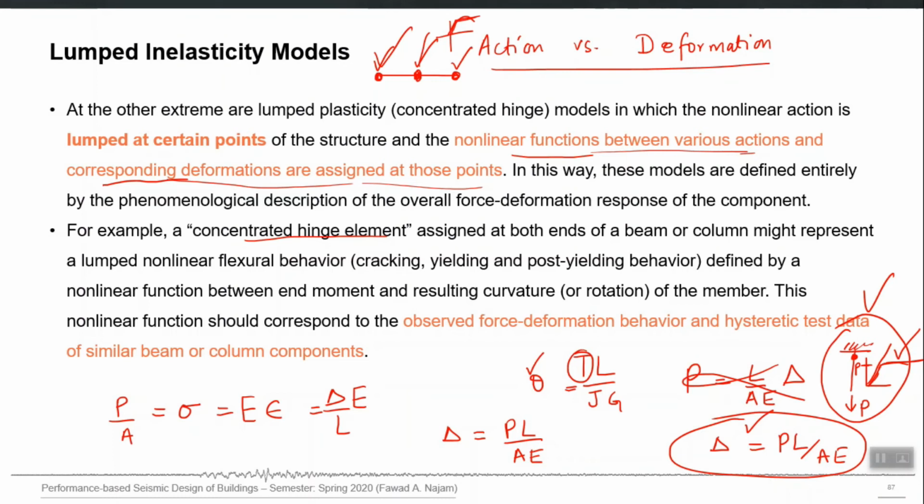These things were not possible in a linear model. Just imagine, shear failure occurring as a result of some applied loading was not automatically predicted in a linear model. It will simply report the bending moment and shear force diagram. Whether the actual beam will be able to sustain that bending moment or shear force, that model was not able to tell, but this nonlinear model will be able to tell, right? Because it has certain points in it in which we force it to follow a nonlinear behavior.